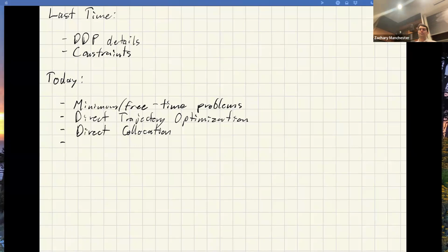And then basically the way these methods work is you do a bunch of discretizing of the optimal control problem, and then you pretty much just stack it up and form a big nonlinear optimization problem. You get into the form of a standard nonlinear program, and then you use an off-the-shelf solver to solve it in most cases. People do write custom solvers, like we do that quite a bit to get extra speed for particular problems, but in general, you can just write the problem down, discretize, and throw it at a commercial solver.